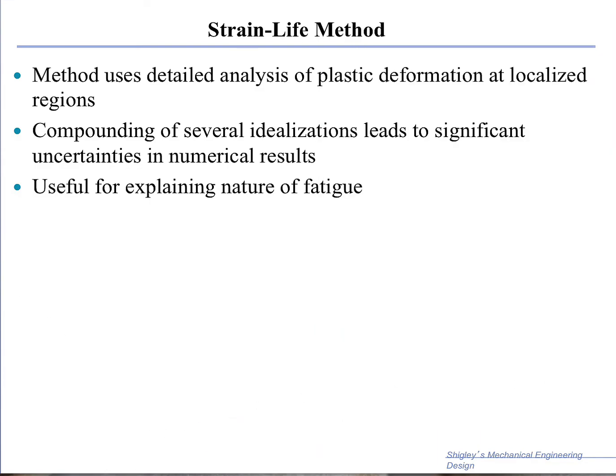So in this approach, we have the strain life method. We use detailed analysis of plasticity, and moreover, we have to include cyclic plastic deformation at localized regions. So that becomes very important.